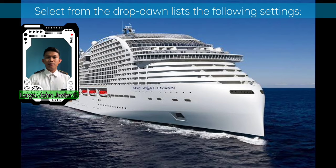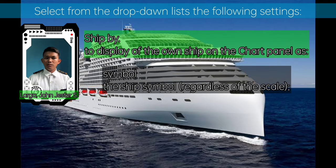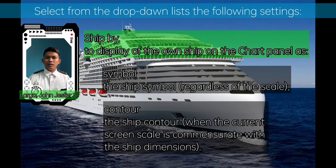3.5.1. Select from the drop down list the following setting. Ship symbol: to display own ship on the chart panel as the ship symbol, regardless of the scale. Contour: the ship contour when the current screen scale is commensurate with the ship dimension.